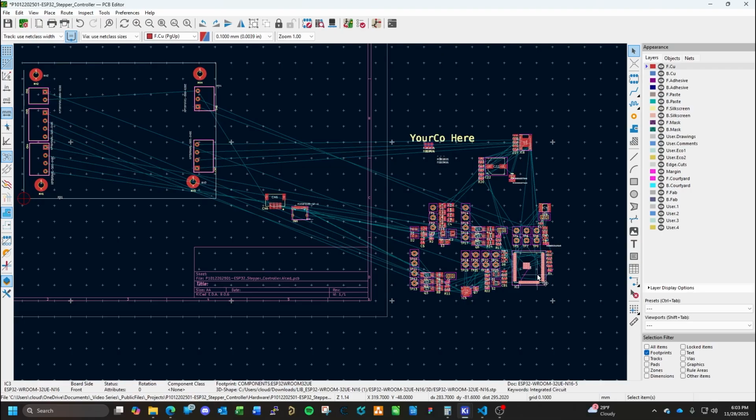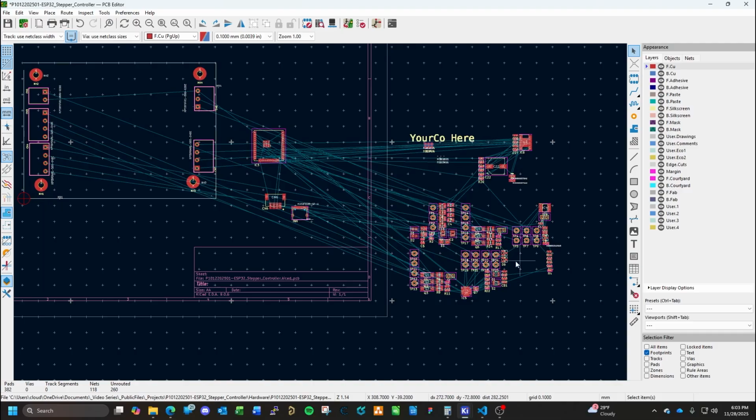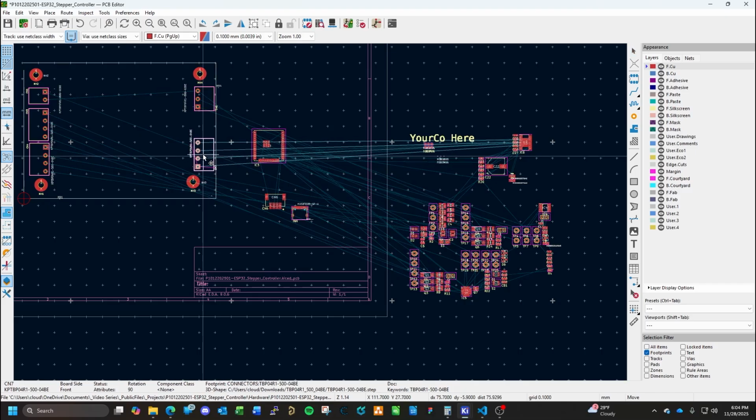And then we have the next big part, the ESP32 itself. Again, we can populate a lot of this on the bottom, especially the optos, the resistors for the optos, other components if we absolutely have to. Not a big deal. The motor controller, we could, but it'd be better to populate it up here, close to this, to reduce the traces necessary to drive the motor pins. So we'll just plan for that.